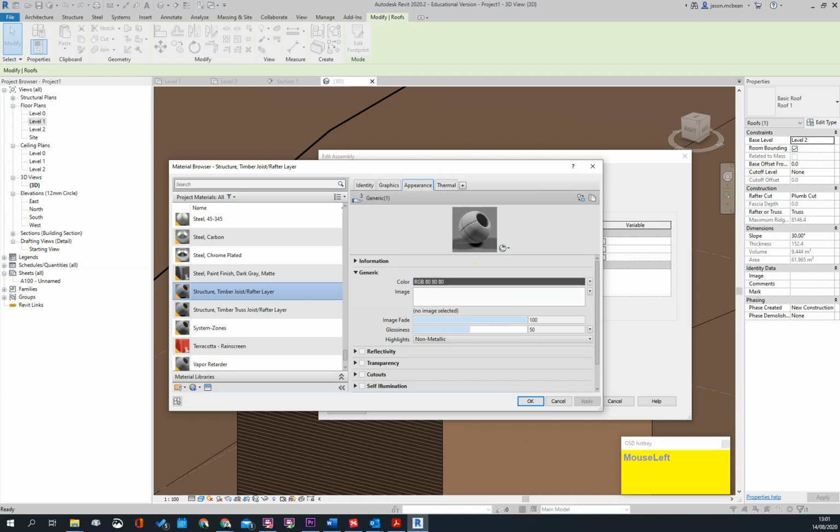When it comes to determining its substrate, I'll explain this in a second when we use the override of the line material, but generally you want structure to join with structure, substrate to join with substrate. So if another roof had to join this, it's just how they join. You give layers hierarchy so that a structure will always join with structure and a substrate will always join with substrate. I'll show that when I draw a section of wall as well.